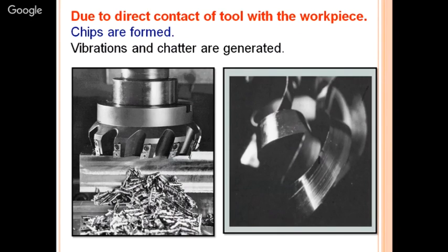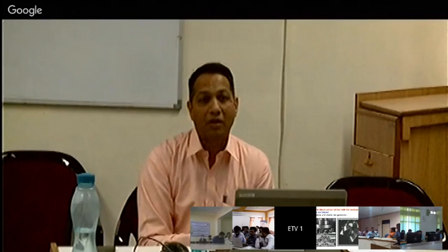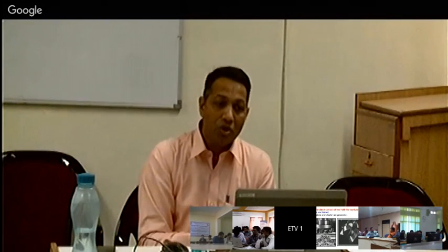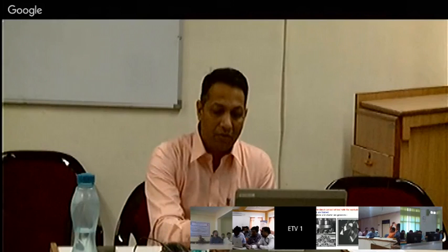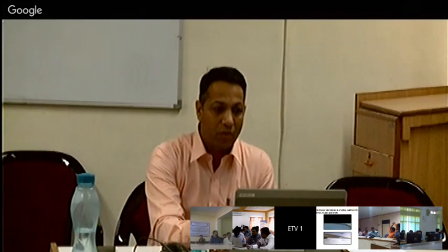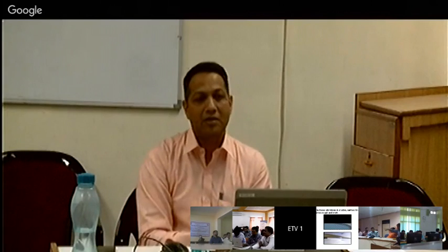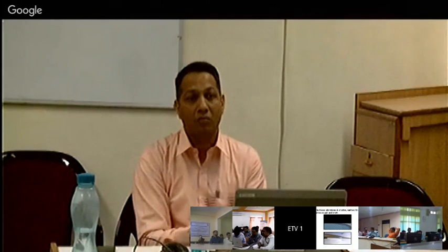Intentionally we make the tool stronger to remove the metal from the surface of the workpiece. Otherwise it would not happen, and the tool would become blunt. So there is a fight. Now you know when there is a fight between two persons, there are vibrations. So vibrations and chatter are generated by the fight between the workpiece and the tool. This is undesirable, but we cannot remove it.